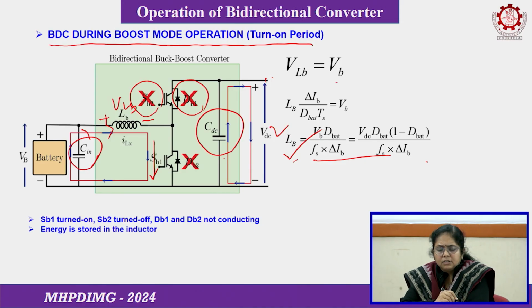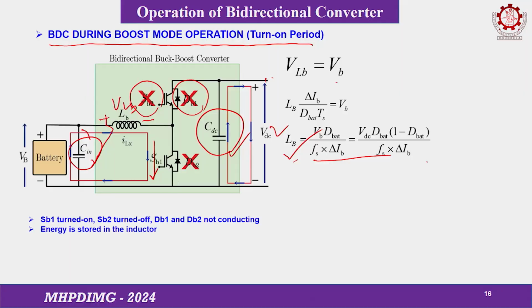For the capacitors, what is required is the ampere-second balance technique, which you can use to calculate the input and output capacitances during buck mode or boost mode, that we will see. So, this is about the boost mode when the switch is on. But when the switch is off,